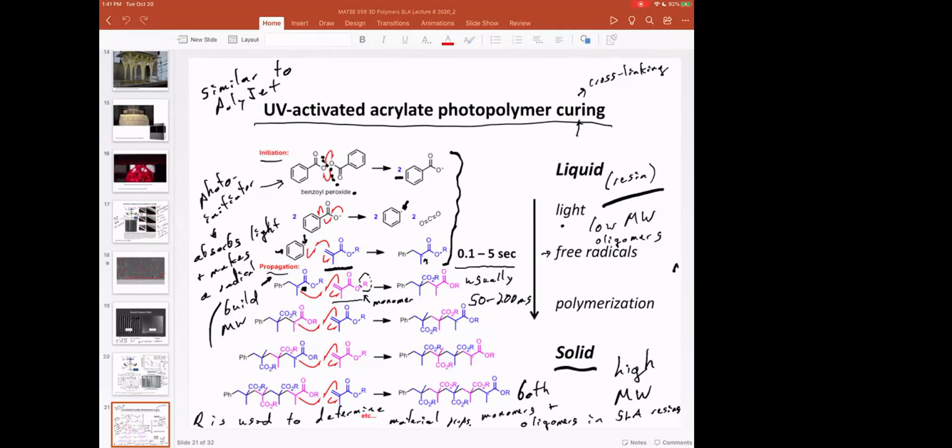And then in Cura, which is going to be your slicing software, that's where you tell the printer what material is what and which nozzles are going to print which material. Cura generates the G-code, or the instructions for the printer. That's where you say, I'm going to use ABS for this part, and I'm going to use PLA for this section of the model, and then here are the parameters for all that.